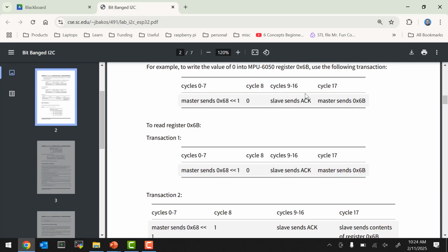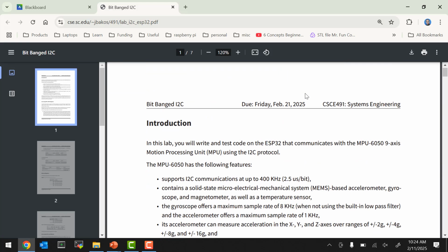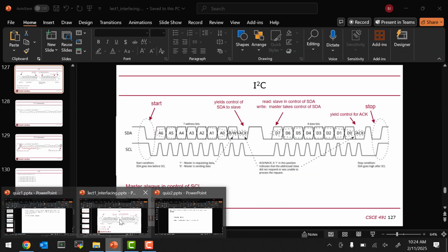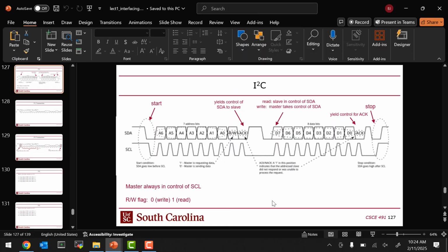So that's the way that you read and write I2C. Now, there is a separate protocol for the sensor itself, and this is where things are a little weird. All the examples I've shown you with I2C have been a single address sent, and I didn't really say what that address was meant to signify. You probably assumed it was like a register address, like with programmed I/O, and then there's a single byte of data. It's a little different with how this sensor works.